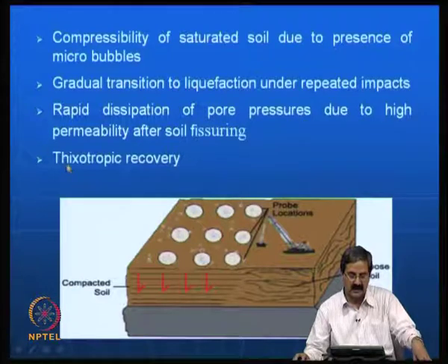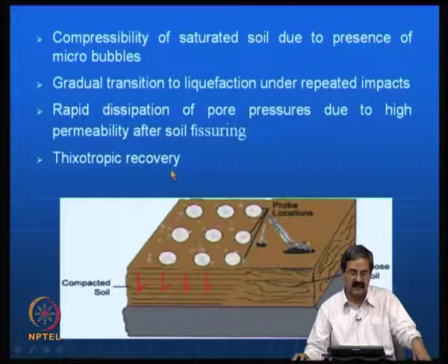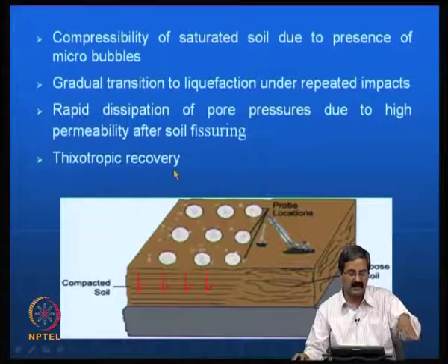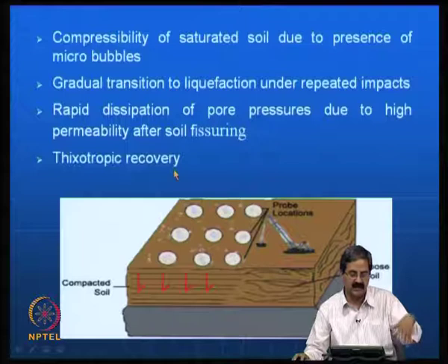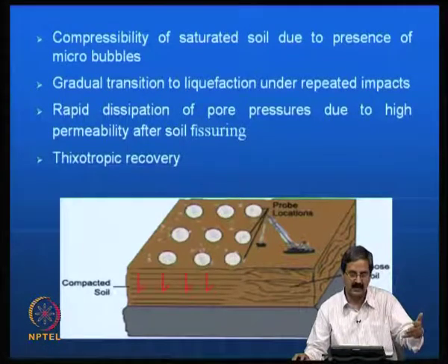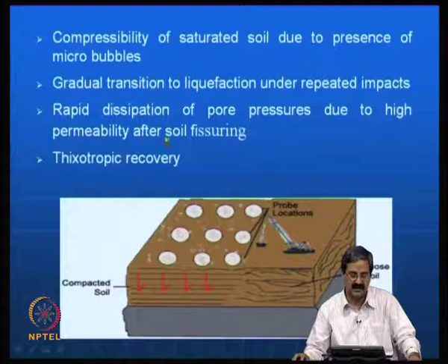Then there is what is called thixotropic recovery. There is so much energy imparted into the system, and with time there is also a mobilization of strength because of all these other three effects.